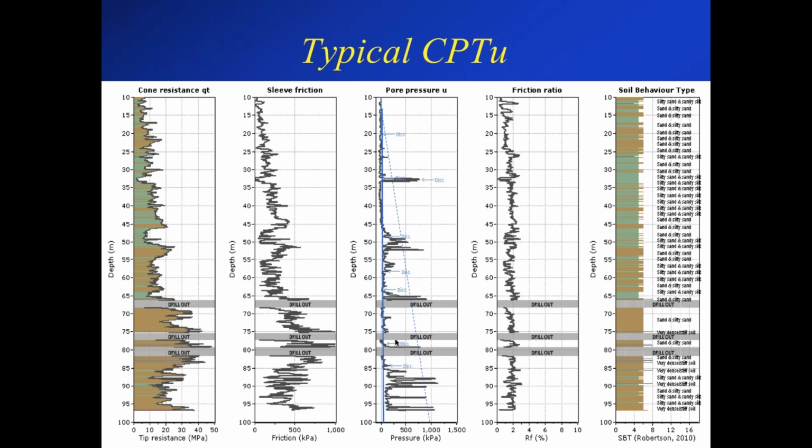So here's a typical CPT. It's the one at the highest section. So it's pretty impressive. This is 96 meters deep. So it's pretty impressive that they're able to push CPT through this material. If you look at the cone profile quite carefully, you can roughly see sort of 20 to 30 meter lifts. You often see a little drop in the cone resistance, maybe where the lift boundary was.